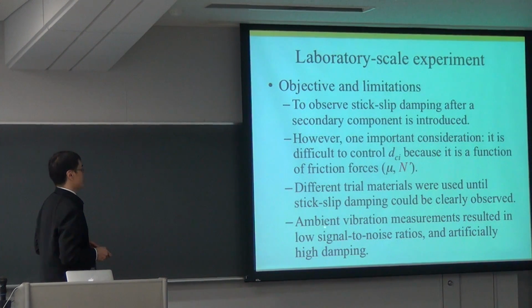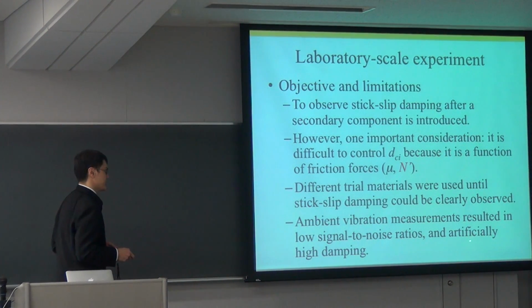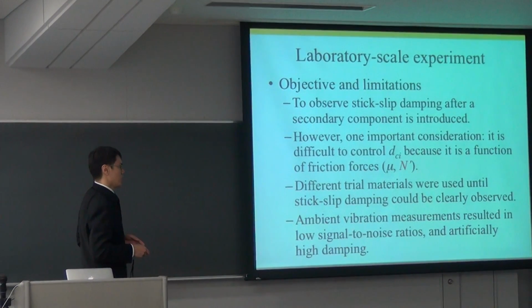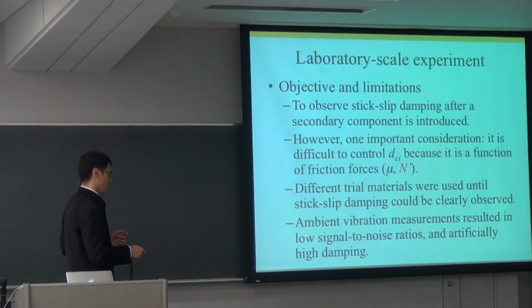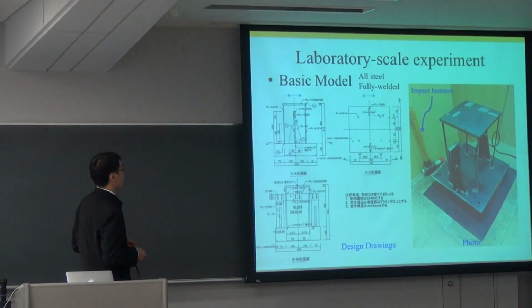And I should also mention that I did some ambient vibration measurements, but they resulted in low signal to noise ratios and therefore artificially high damping. So I'm not going to talk about ambient vibration measurements here.